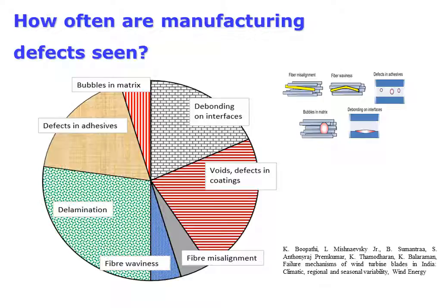Further, interface defects, like delaminations and debonding, build the largest group of blade defects. This is an interesting conclusion, potentially useful. When we remember that composite buckling is triggered by weak interfaces, it can give us a hint how to improve the blade quality.